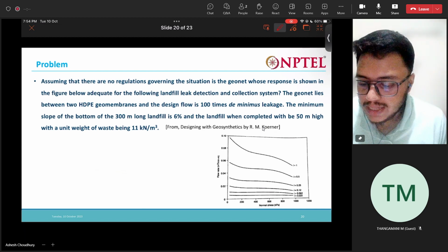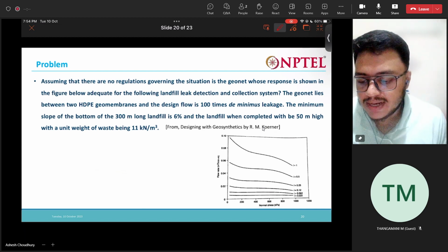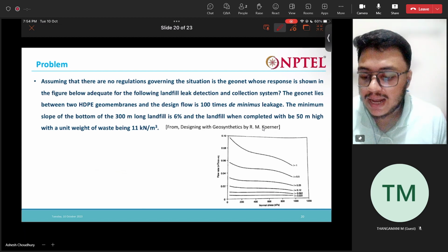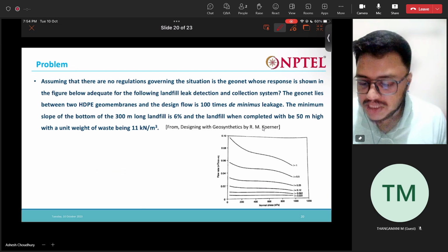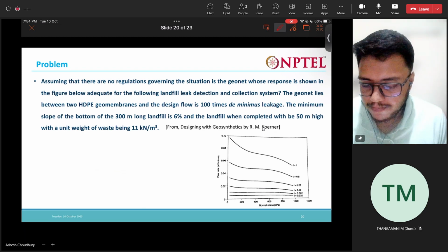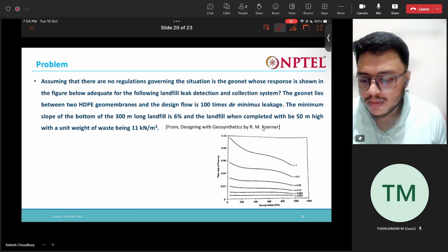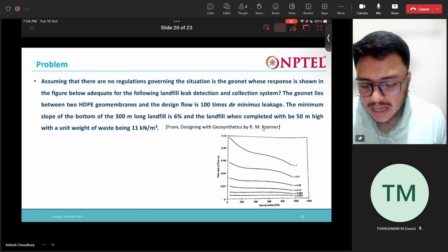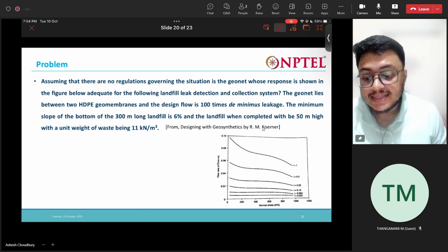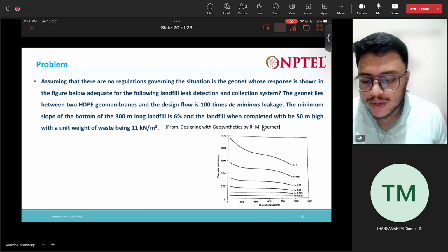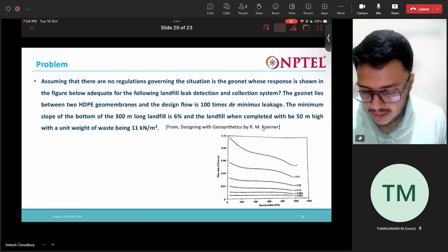The primary or upper geomembrane of a hazardous waste facility should allow no more than de minimis leakage of all polluting species through the liner itself. The concept of de minimis comes from the legal principle de minimis non curat lex. De minimis leakage is considered to be the amount that is of no threat to human health or the environment.